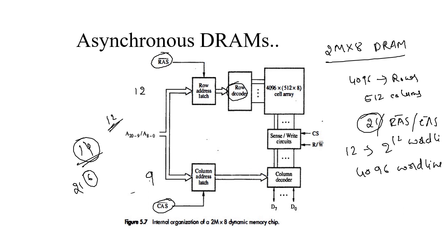For example, if the 12 bits are all 0 and given to the row decoder, then the output of the row decoder will enable the W0 word line. When the inputs are all zeros, word line 0 will be selected.